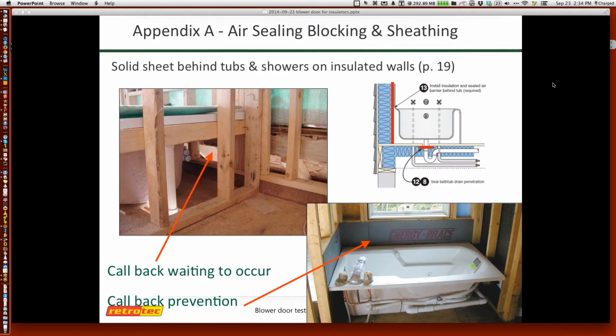So here's some examples of, this actually is the eave over here by this bathroom. So it actually has air infiltration that goes to the tub and whatever's next to the tub, probably the toilet here. And once it's in the wall, it's moving throughout the structure in general. So all things must have an air barrier associated with the entire envelope.